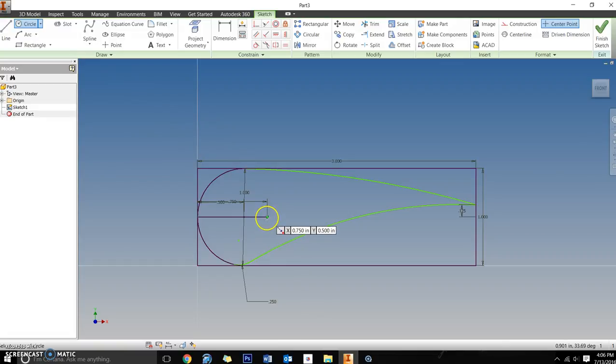Again, you want your dowel rod to be in the first third, okay, of the airfoil, the upper third of it. All right, and again, that just helps when you're creating the angle of attack and you're testing it. Gives you more accurate results and things like that. More true representation of what would actually happen if this was a true wing on an aircraft. So we're going to make that 3/16.